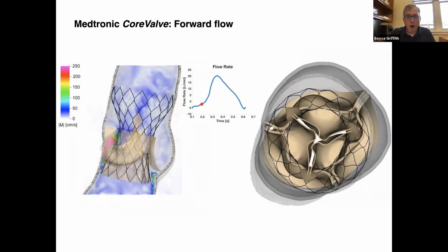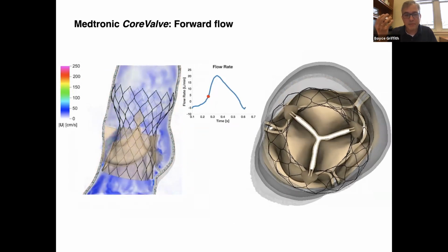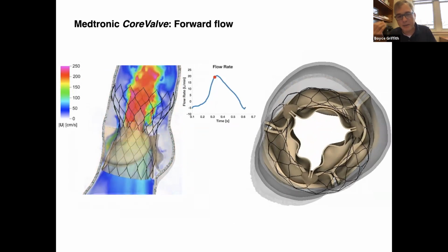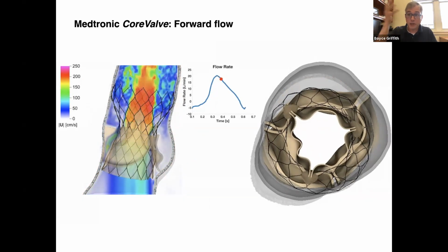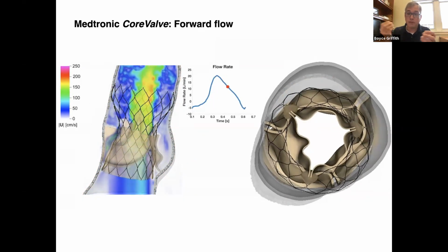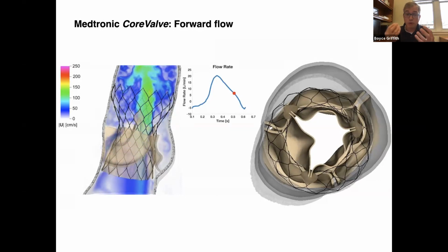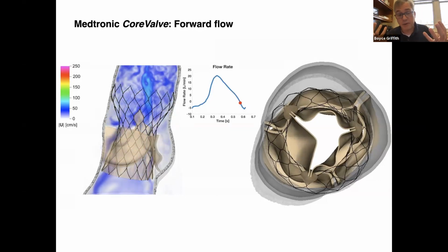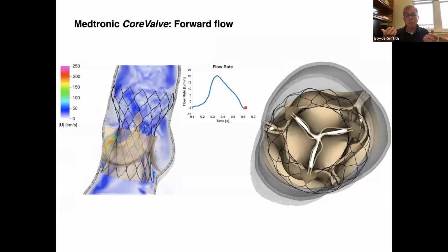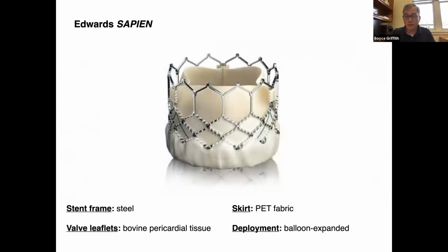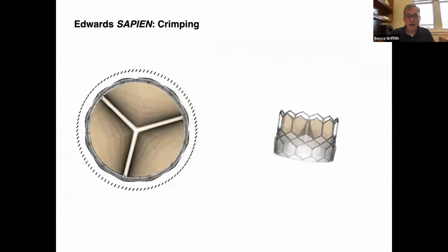So all of the contact here is being handled automatically by the immersed boundary formulation of FSI. In particular, we're directly simulating contact between this transcatheter device and the model of the native aortic valve. And with these kinds of methods, they have pluses and minuses, but one plus is that you don't need to have predefined contact surfaces in order to model these kinds of contact problems.